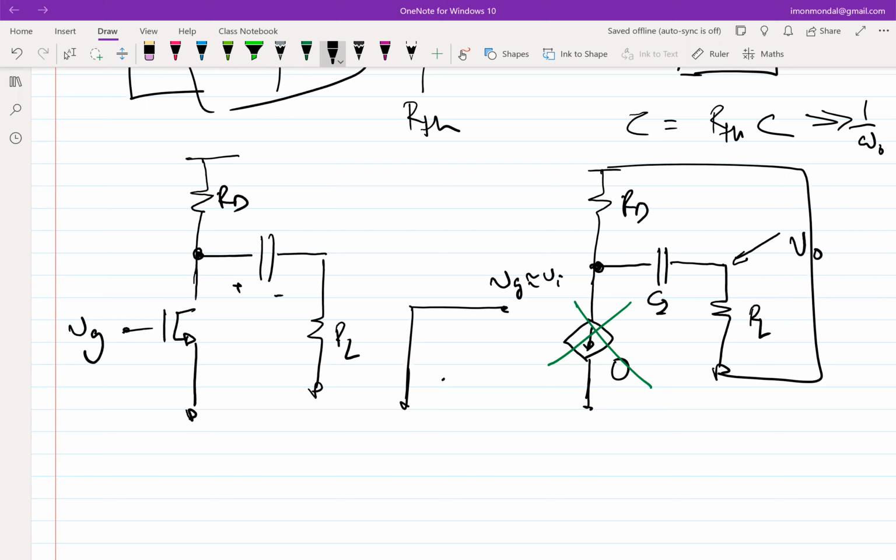Focus on the right path. Correct. Same kind of expression, looking into the time constant, right? Before the midsem, we were looking into this through the Bode plot, but we are trying to equate whether those two are identical. So now, what will be the time constant associated with the capacitor? C2 times RD plus RL. And this should be much, much greater than 1 over omega. Right? So time constant methods are extremely simple once you figure out how to find the time constant.